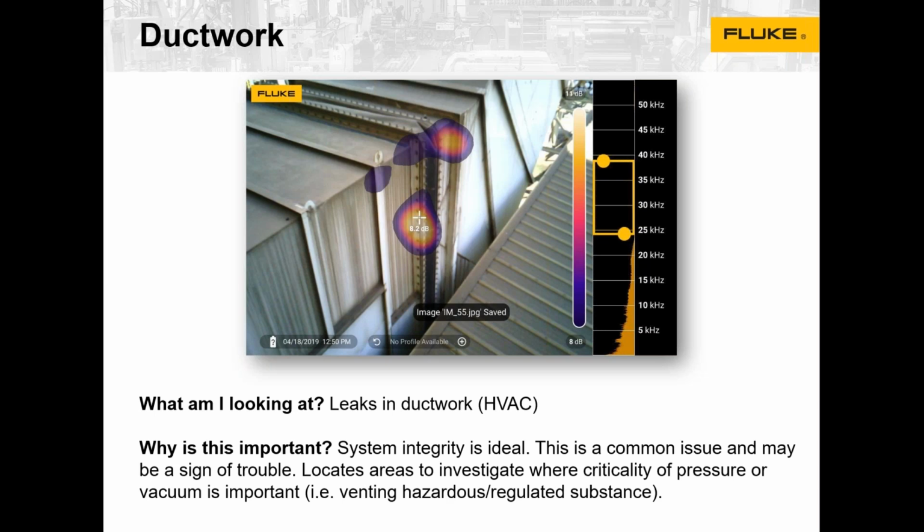Yeah, I've been on site at a couple of the customers that have exhaust systems or ductwork like this to suck some of the off-gassing or some of the byproduct of their production process out of their facility. And one of the other things that I've heard IN900 being used to identify leaks, or the importance of it, is really about safety for the employees. If too much of those noxious gases or that off-gassing or byproduct gets into the facility where their people are working, it can definitely impact their health. And so that was one of the things that really stood out to them: we've got a commitment to our people to give them a safe working environment. So if there's a tool that can help us identify these vacuum or negative pressure leaks in our systems that are intended to keep people safe, it was absolutely worth implementing a program to do that.